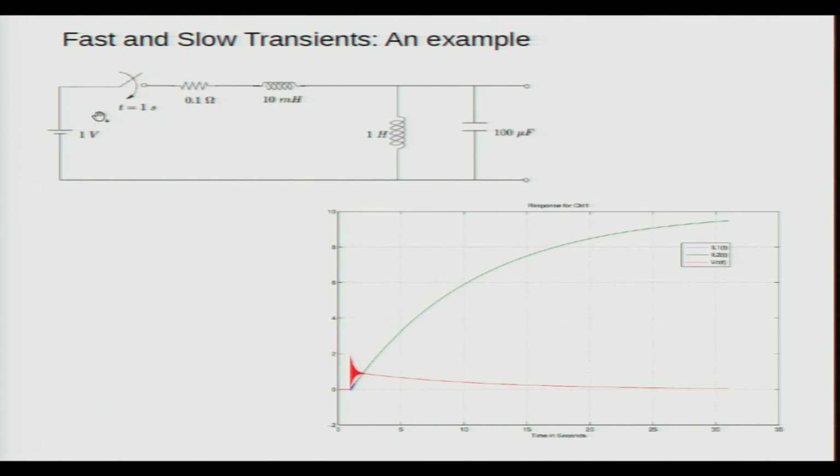One is the one being shown. The second loop is between this. So, there are 2 differential equations there, and the third differential equation comes when you apply Kirchhoff's current law to this node. So, you will actually get 3 differential equations, and again if you assume the input to be K e raised to (st plus alpha), you can get the steady state response in the manner I showed you.